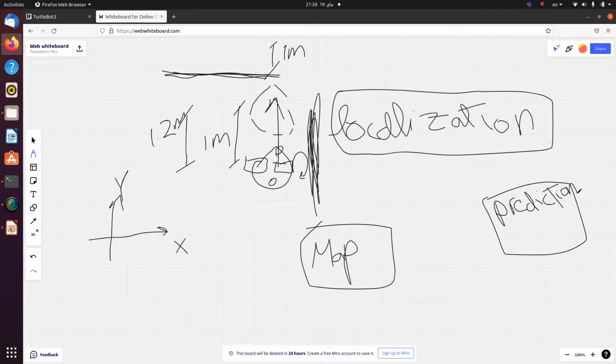Then, if I provide a voltage V for a specific period of time t, I can plug these values into the dynamic model and get an estimate of the position of the robot right now. So that's another dead reckoning method.